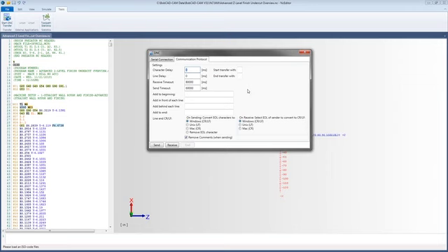Let me just talk to you about this ShopLink Flash and give you a chance to look at it, or at least give you the information to talk to the guy who makes them. RS-232 isn't fun to set up, and I can't find anyone that really has a complaint about these ShopLinks. You set it up once, and then you have access to being able to take a USB wherever you want. The bigger part of it is there's no limitations on the USB. Some guys pay to get a floppy drive converted to a USB on their machine. If you do that, the USB that you get is going to be formatted to be the same size as the floppy drive, so you're not gaining any space out of it. The ShopLink will take care of that, and it'll drip feed for you.